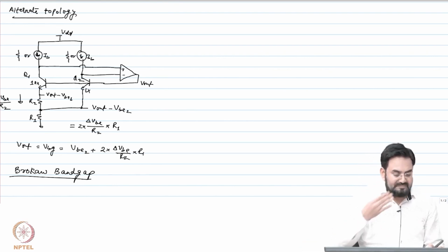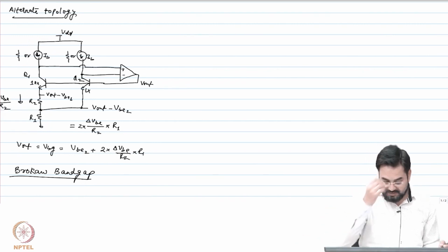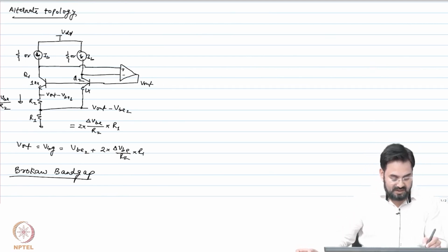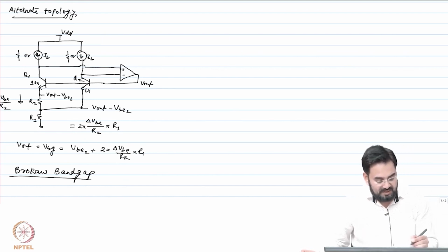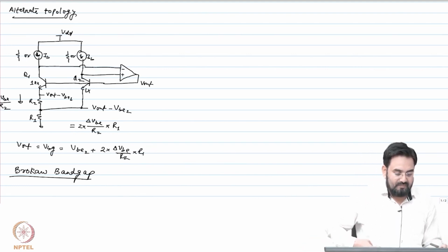Okay, because the reason is this voltage should be higher and the bottom side of R2 should be lower, and you make it 10x, so that Vout minus VB will be larger for this. And now you have to flip the polarity of this to make it negative feedback. Okay.